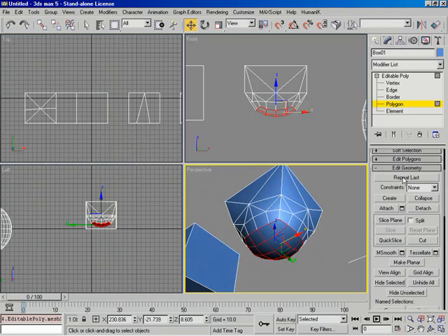As I continue, let's go ahead and do a repeat last. As I continue, it continues to refine it, making the original polygon that I had selected appear smoother, smoother, and smoother, more and more round. So when you're using the M-Smooth command, you have to manually add iterations of smoothing. Exactly, by clicking M-Smooth again and again. Absolutely.